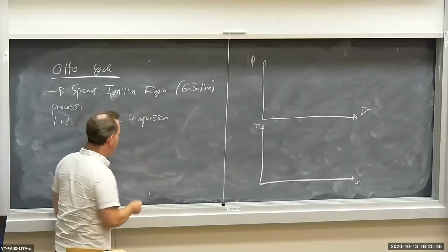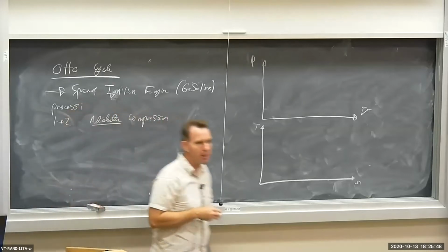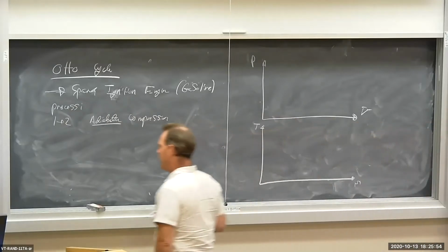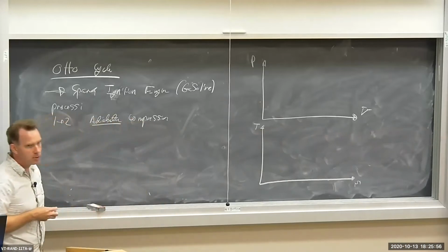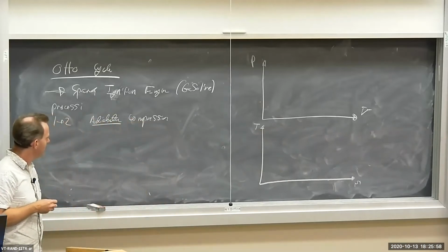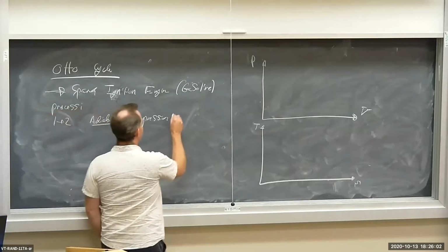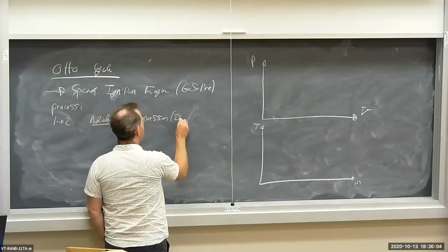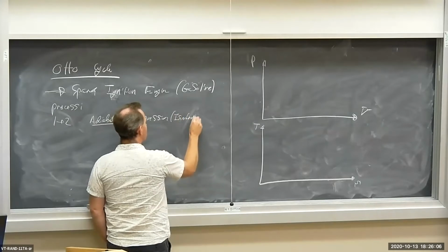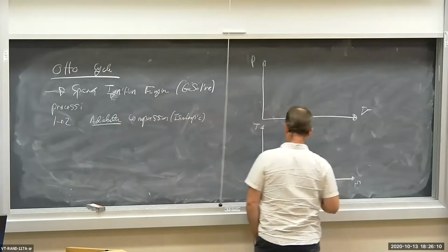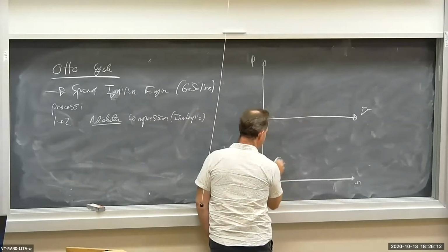By the way, if it's adiabatic, you apply the entropy balance, assuming air standard cycle, of course, no irreversibilities within the piston cylinder device, within the system. If it's adiabatic, it also means that it's isentropic. So it's also isentropic compression. So here's state 1 right here.